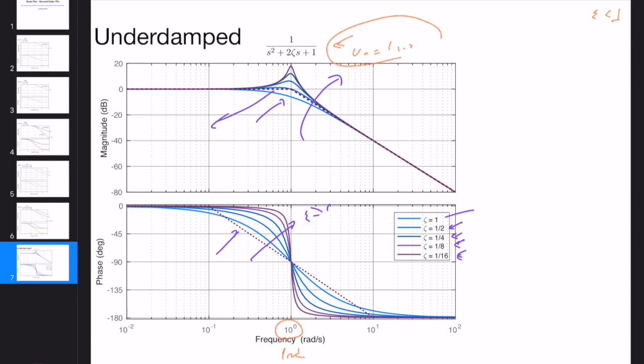It's kind of weird because the biggest error, of course, occurs when psi is equal to 1 over 16, and it will be even worse for smaller psi's. But the best approximate response is not occurring when psi is equal to 1. Instead, for this case, psi is equal to 1 over 2.